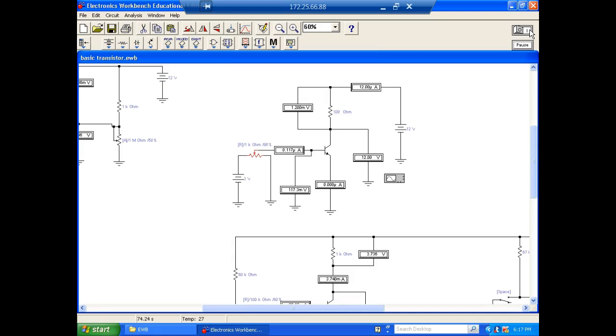So here we come up. This is 100 millivolts, still 12 microamps on here, so it's not doing anything. Okay, 180. I'm going to start jumping up pretty fast, guys. So here we're going to get up about 300 millivolts. 400, 500, here we go. Now it's just now starting, but we're still in that knee, right? We're getting a little bit of collector current, but we're still almost cut off. 600 millivolts, still not there. We're up to about 15 microamps. This guy's going to cut on probably right around in here. I think this guy uses 700 millivolts.